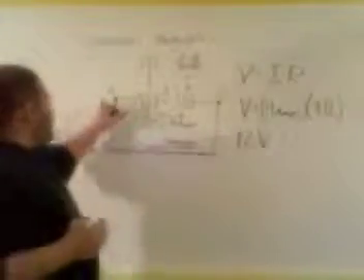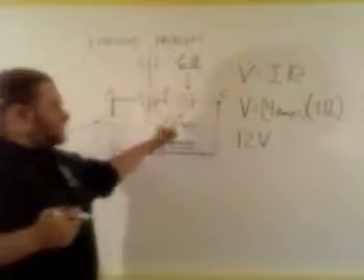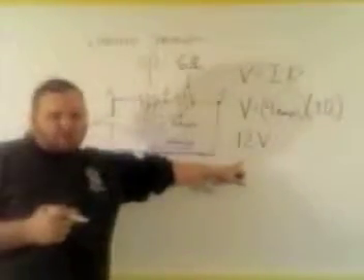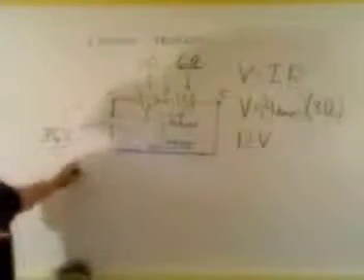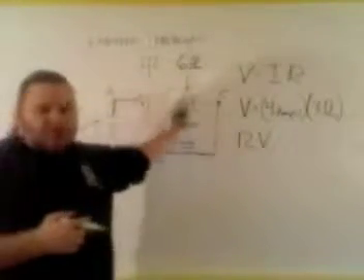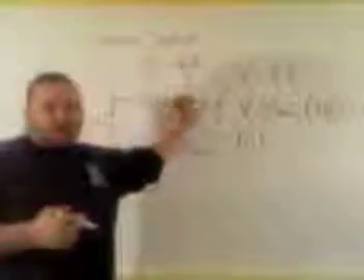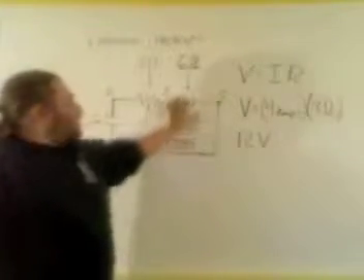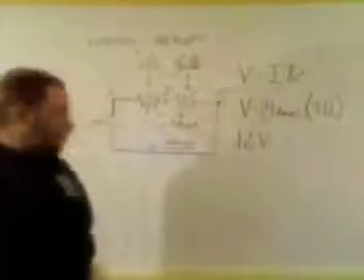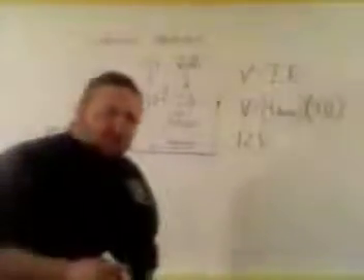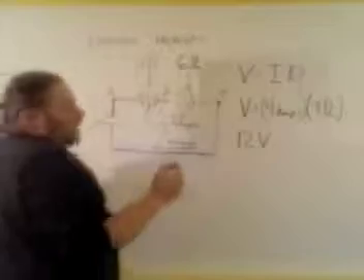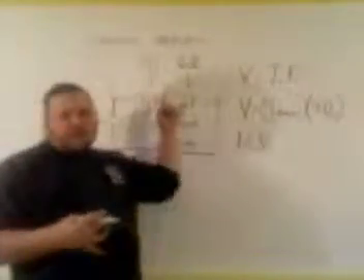That means that after it goes from point A to point B, my potential will drop by 12. So if I started off at 36, I've now dropped by 12, so now I'm at 24. I have 24 volts coming across the 6 ohm resistor. Okay? Cool? So what I want to do is calculate how much voltage is consumed in that 6 ohm resistor.